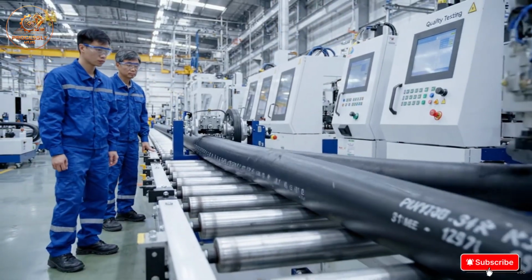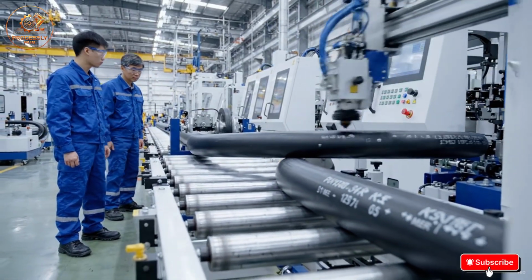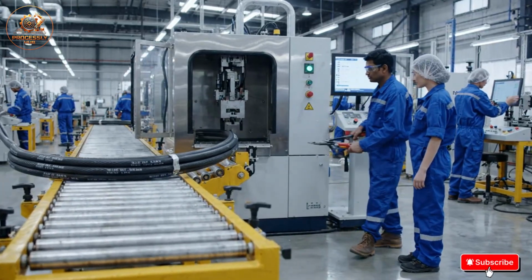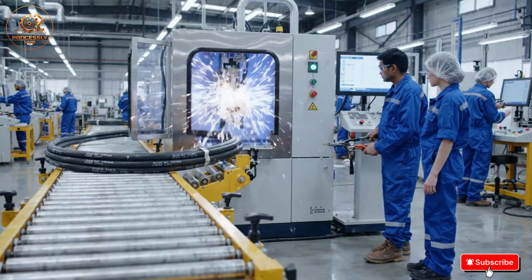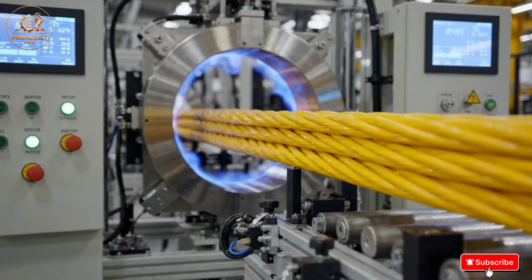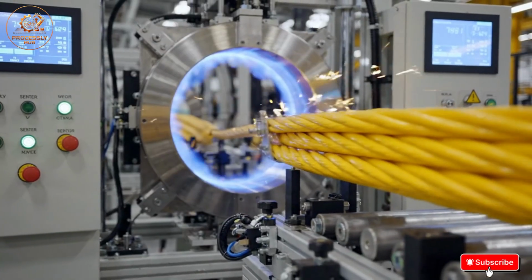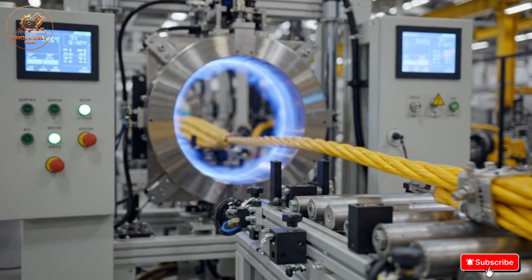Next, every cable will undergo rigorous quality testing. Every finished cable must pass strict quality inspections. Testing ensures safety, durability, and electrical performance. A high-voltage spark test detects invisible insulation defects. Any pinhole or crack is immediately identified.